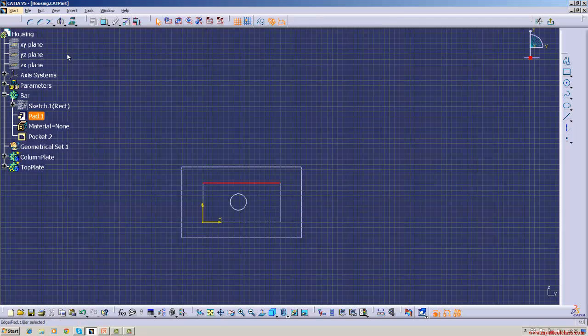what you have to do is, as usual, you take a 3D point projection, 3D point projection, now you can draw the sketch. So you have to click this because it is a drawing line. It is not a construction line. Like this.